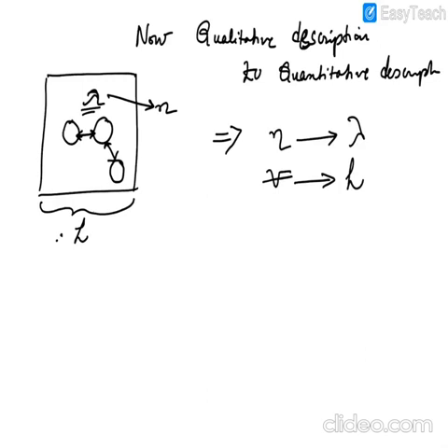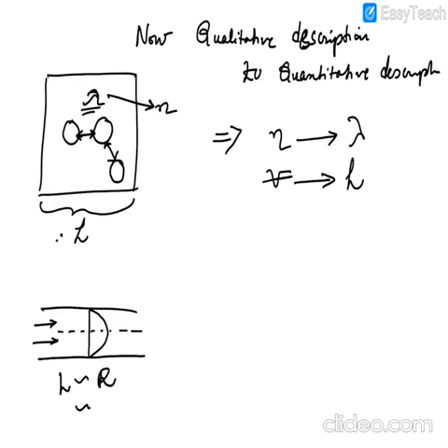Suppose you have a flow of fluid in a pipe and you see the variation of velocity across the radius. The characteristic length is the distance over which the change can occur. For a pipe it scales with r, and in engineering practice, instead of r, 2r, the diameter of the pipe, is more relevant. But it doesn't really matter when you are talking about order of magnitude. The only thing it scales with is the radius.